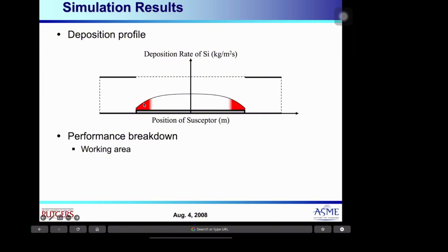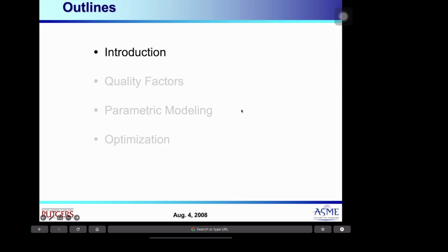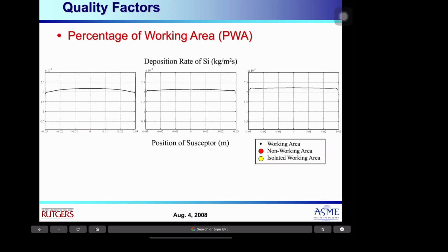If I can control the temperature of the furnace and the speed, we realize this deposition profile will be changed. Some simulations show that it's possible to have a pretty flat deposition rate. The only question is what the optimal temperature and velocity are.